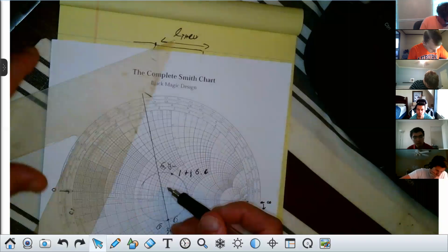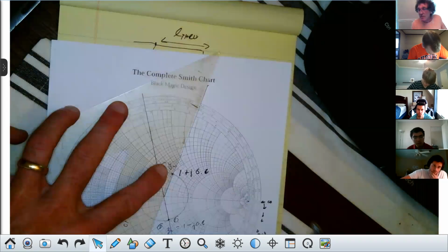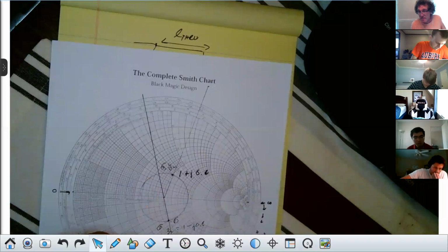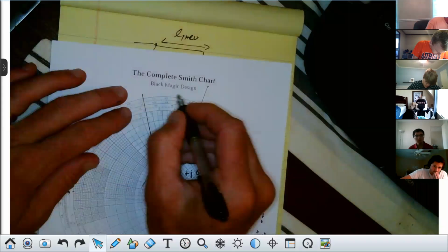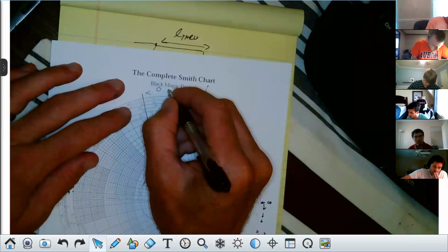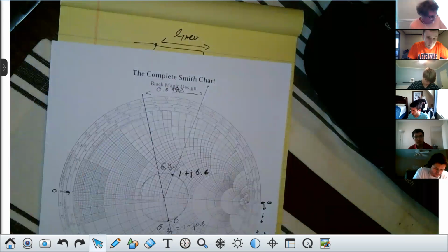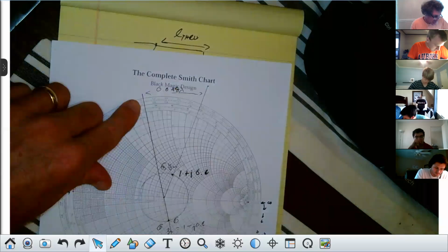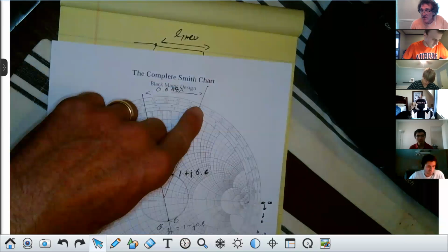Okay, and that's exactly what we did with another element before, right? That was a capacitor, right? We put a capacitor that distance away in parallel. Correct, class? If you remember. So what is this distance? Does anybody still remember it? Wasn't that 0.048 lambda? Y'all remember that? It's not exactly on mine, but it should be about 0.1 lambda, and this should be about 0.148. Y'all remember this, class?